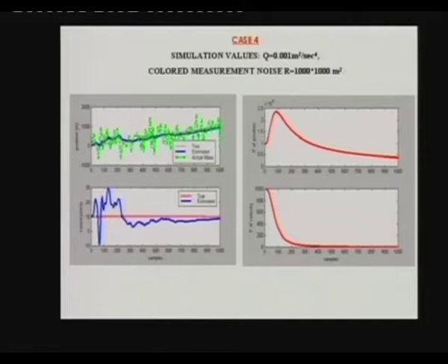See, this scale is significantly higher, again the cursor is gone, this scale is significantly higher, this is 0, this is minus 1000 and the top one is plus 1000, previously it was 200, 400, 600. So the scale is much higher. Whenever the average value of noise is going up, it is going positive, whenever it will go down, it will go negative.